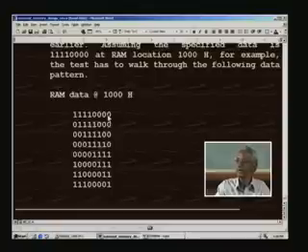And then at the next step, what you do is rotate this one. You may have some sort of accumulator wherein you rotate and then write back the rotated value here. Rotate in the sense that this 0 will rotate back to this position. So, every time you rotate by 1 and then write it as well as check that the data written is correct, and keep repeating, every time shifting, or rather rotating, by 1. When you come to the last one, when you rotate, this one will go to 1, which will be the same pattern as we started with. Therefore, we do not test that condition again.